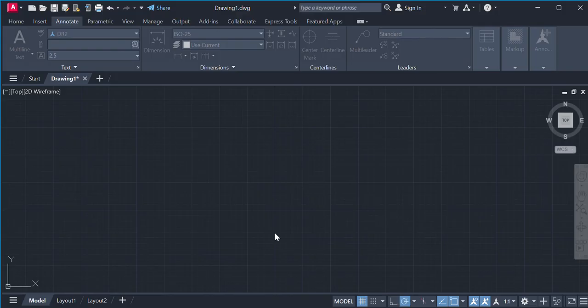Okay. Then offset from dimension line, you can leave it as is. Just make sure that your text alignment is aligned with dimension line. If you said horizontal, everything will be horizontal. If you said ISO standard, then it might change it and everything might not be in the same direction. So just choose that it is aligned with your dimension line.